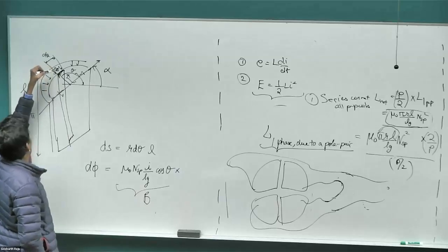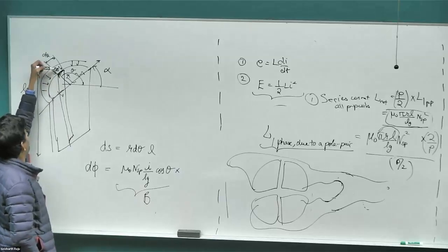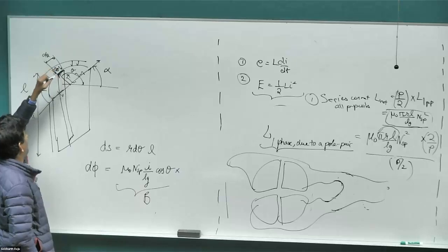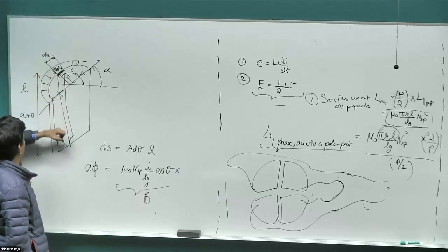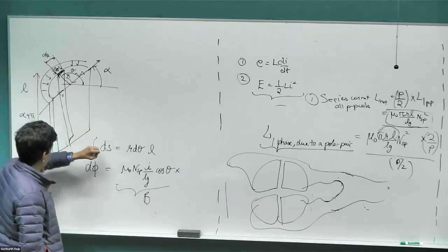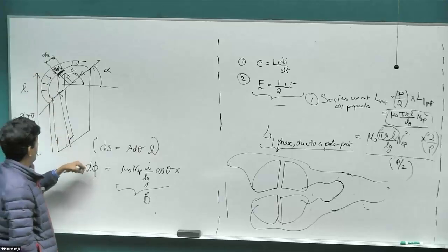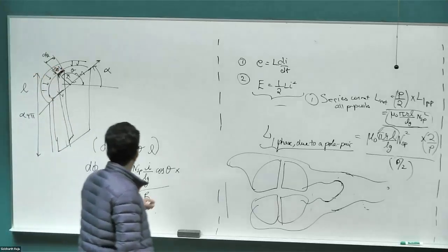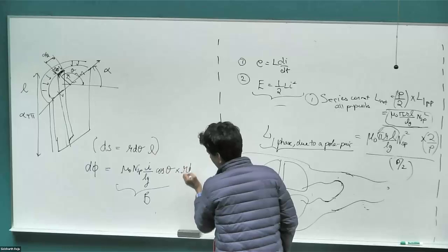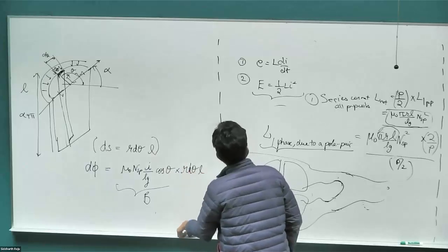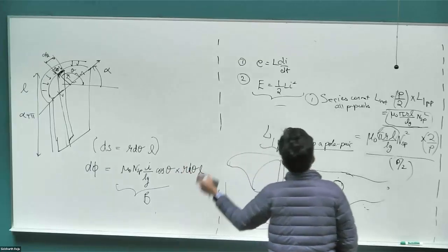B at some angle theta. And if I multiply that B over some tiny incremental cross-sectional area, which is R d theta would be this, and then the length L would be this. So the surface area of the incremental section that I've drawn would be R d theta times L. If I multiply that, I'll get the flux through the tiny section. So I have R d theta times L. Now we are interested in figuring out the total flux.